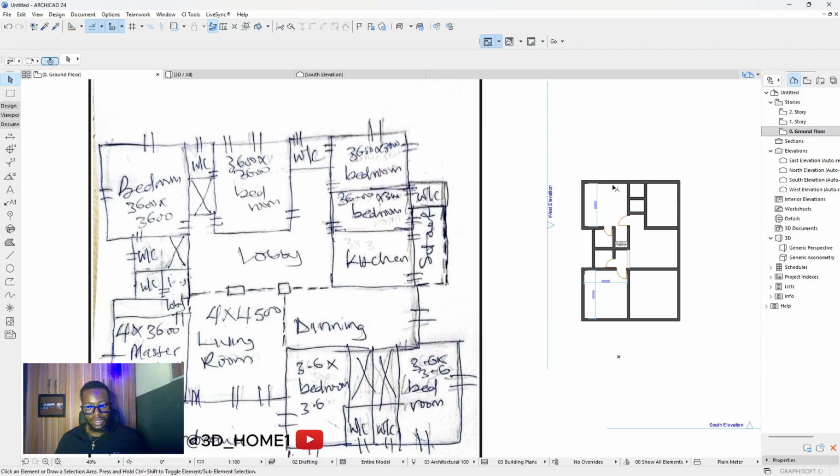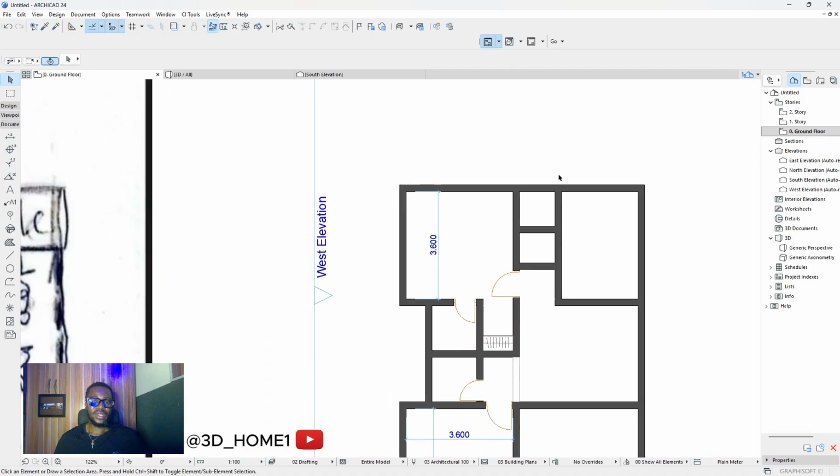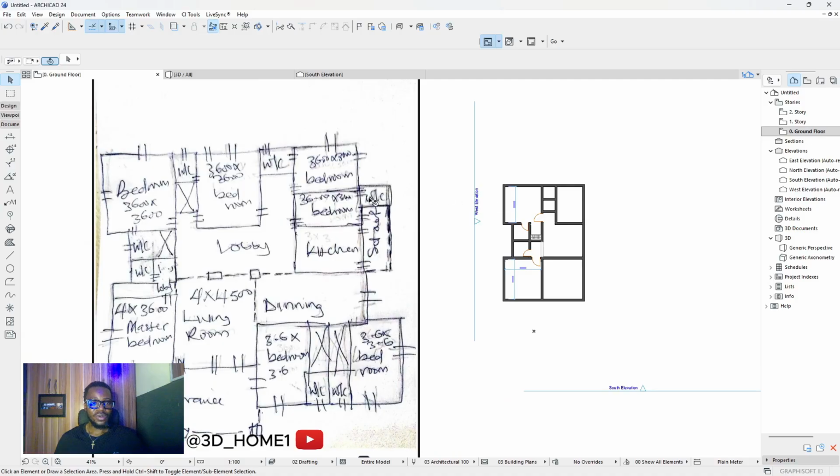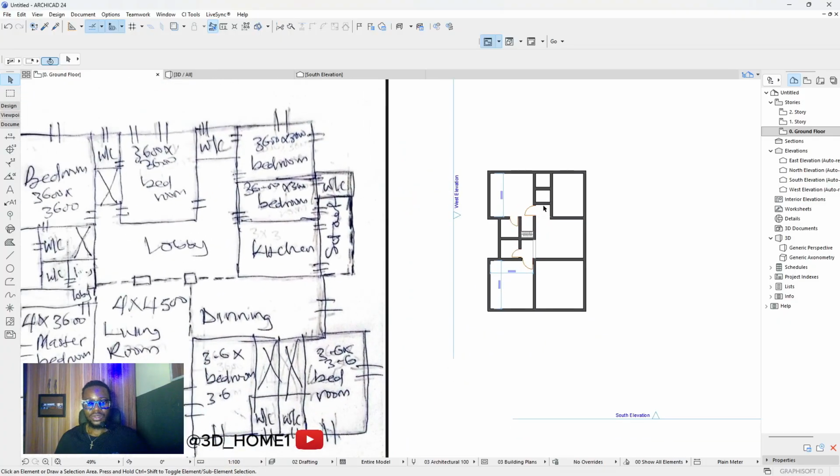Okay. So we've gotten this, but this toilet looks tiny. 1.1 toilet. 1.1 is small. And this is a residential building. You need baths, you need a WC, you need a wash hand basin. So we might just readjust this thing a bit.